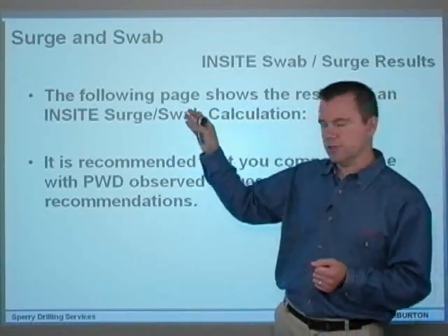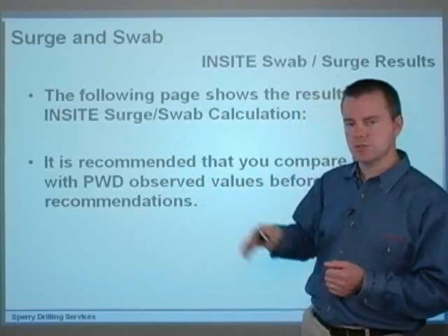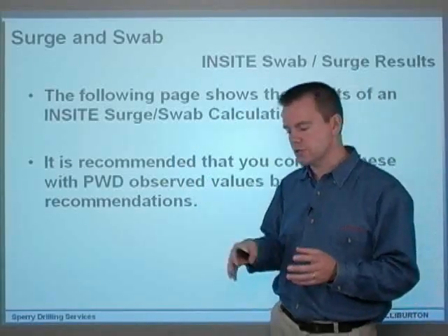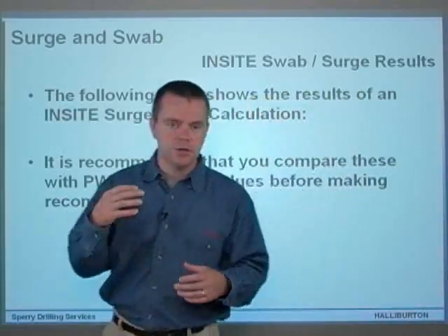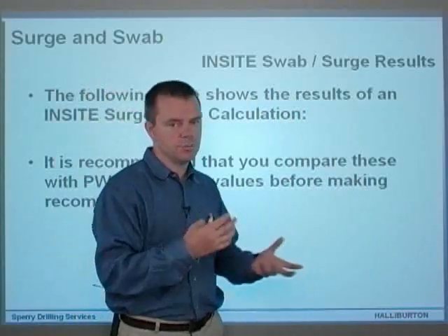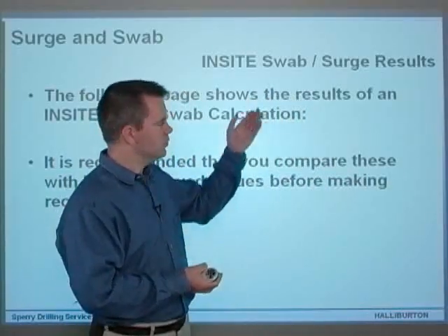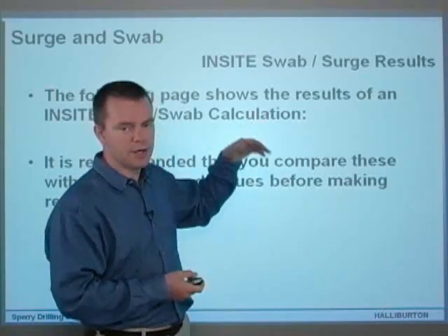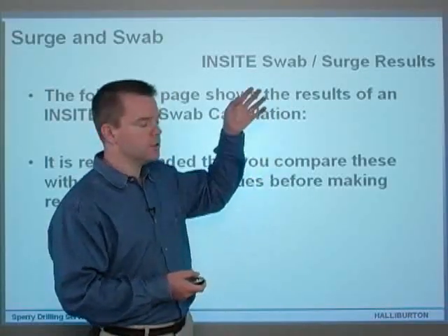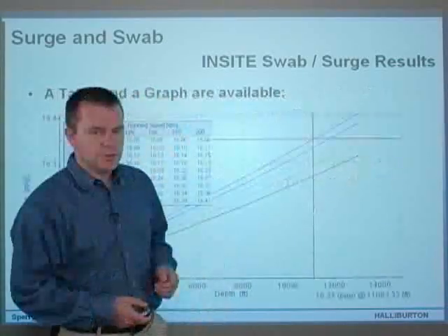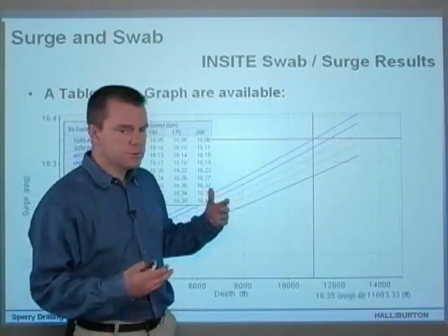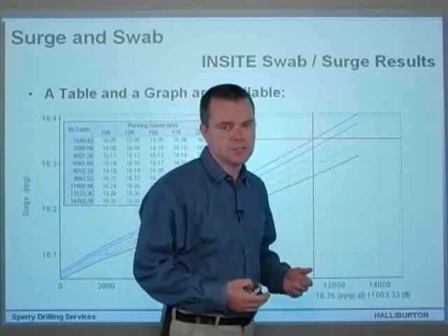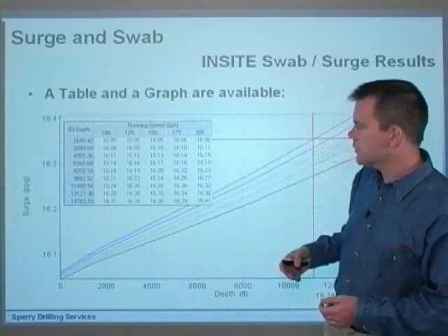But if you can help it, try not to just go with the calculation, because any errors in your geometry or any errors in your rheology or your mud weights that you've put in there will transfer into the result, obviously. So compare reality with the model, and when you know the model's close, use it. Okay, this is the sort of result you'll get on the PC screen when you perform this calculation.